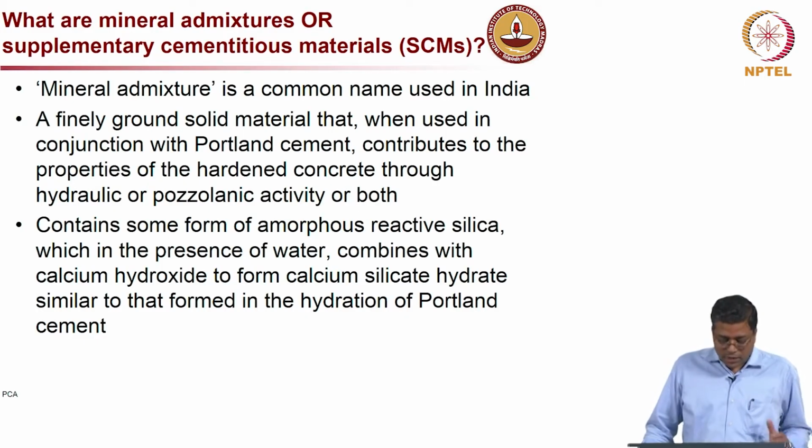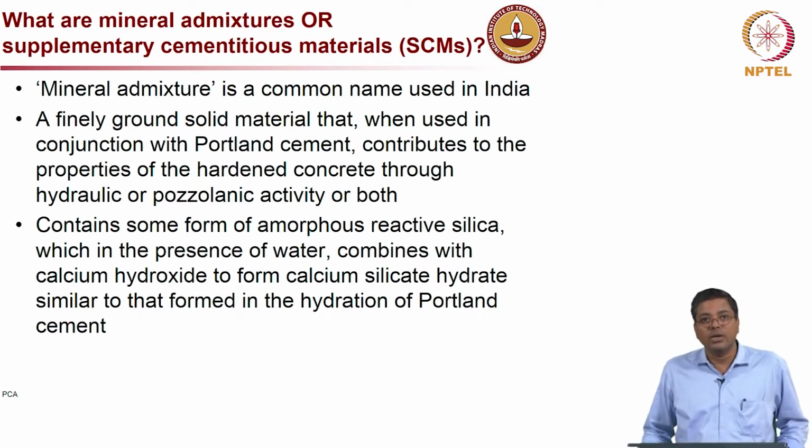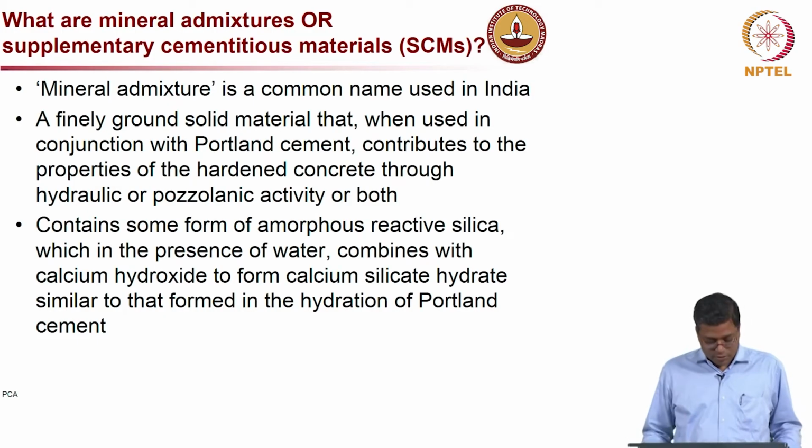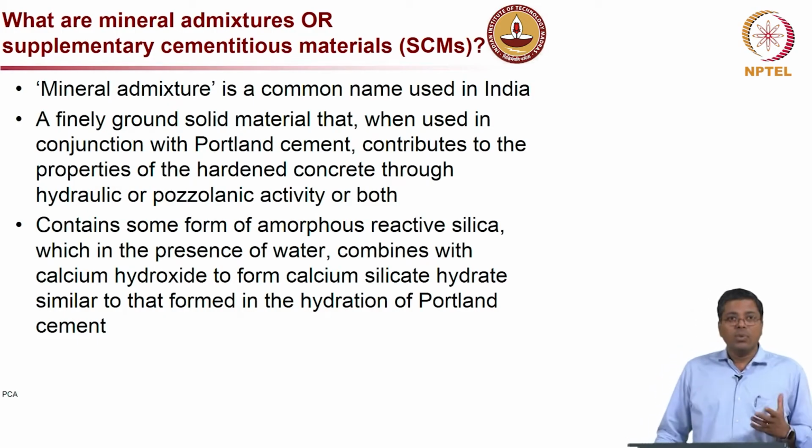Now, what is an SCM? A finely ground solid material that, when used in conjunction with Portland cement, contributes to the properties of the hardened concrete through hydraulic or pozzolanic activities or both. Now, what does it contain?